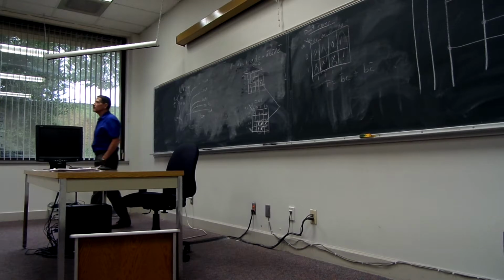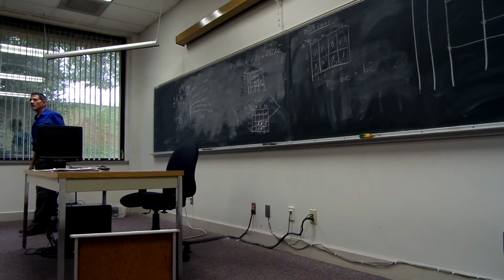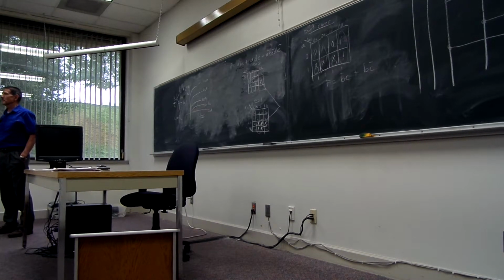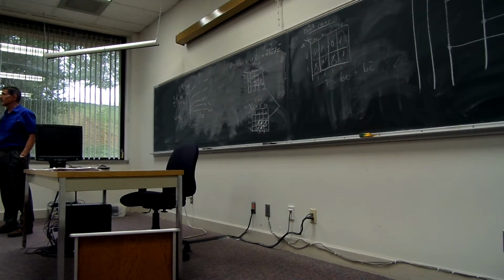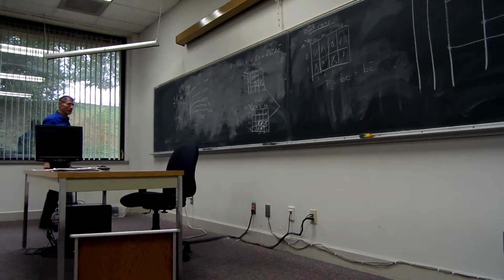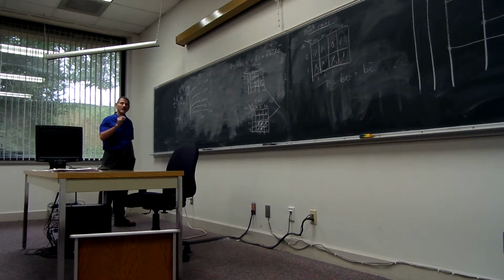Does that mean you could not put in 35 microamps? No, you just don't show that line. Remember, this is a family of curves, and we're just showing what would happen for step changes in the base current.